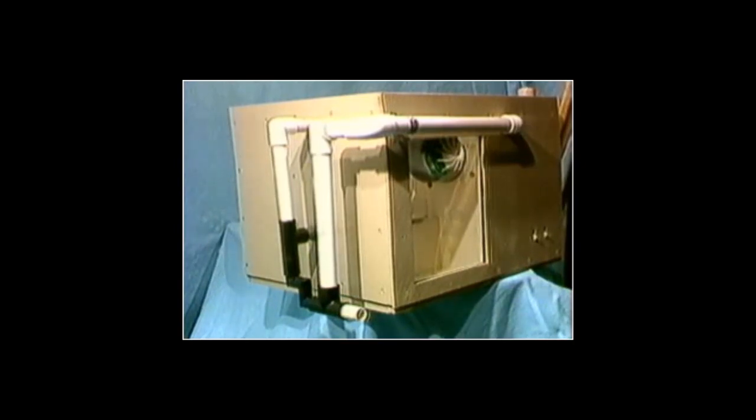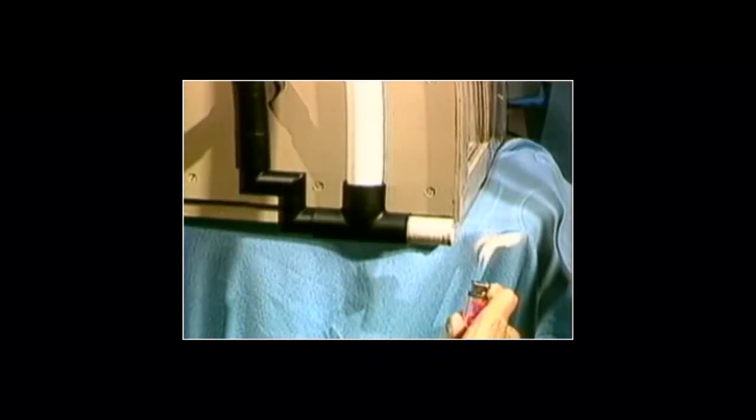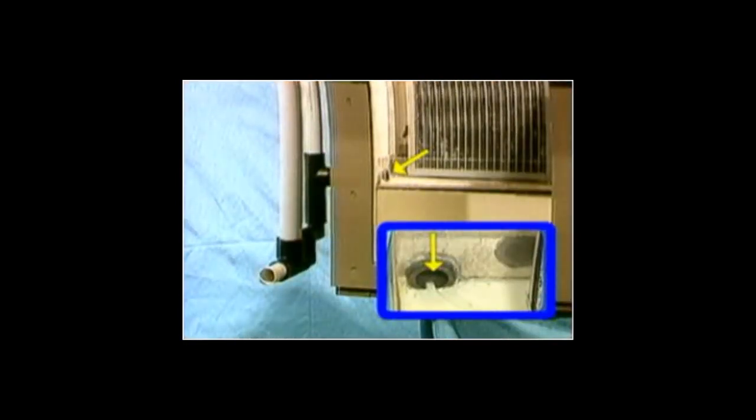CostGard condensate drain seals will operate successfully with internal negative pressures of 5 inches of water. The CostGard device being demonstrated here is operating at a negative pressure of 1.5 inches of water, typical of air conditioning systems of up to 30 tons. Note that the benzene lighter flame is being blown away. Thus air and pollutants cannot enter through the drain connection. Note the two views. In the inset, observe there is no blowing of condensate. Note also that flow discharge is smooth.